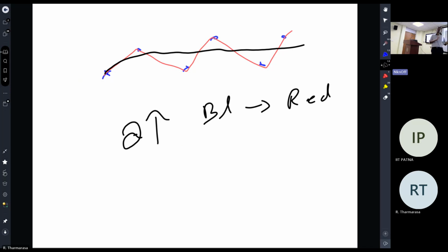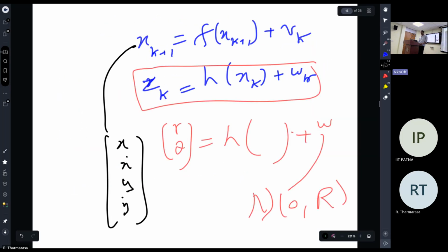The idea of the Kalman filter is that if you know the state, even before you get the measurement, you know more about that particular location. But with larger noise, you can't say much about it. That's why it's harder for the drone and pedestrian, because they are going to make high maneuvers.